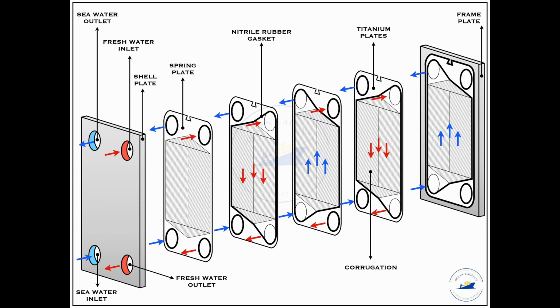It is important to know that when we are opening up a heat exchanger, the box back has to take place in an order, that is the original stack order of the plate type heat exchanger. The plates should not be intermixed under any condition, because I have already told that the corrugations are separate, the gaskets are separately arranged in different directions, as well as the telltale holes will also be arranged in the same manner. So the plates are not to be confused amongst each other.